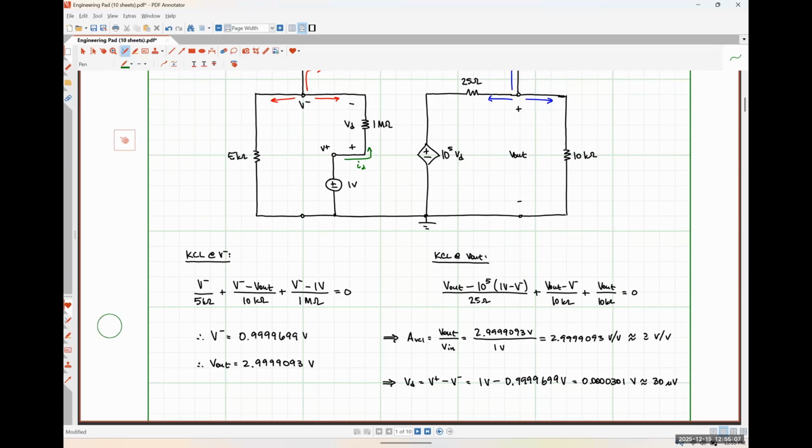All right. So now I want to find the system input resistance and the system output resistance, okay? So unfortunately, these calculations are going to be a little bit harder to do. So the system's input resistance is typically calculated, and we actually talked about this on the second class meeting, we apply a test source across the input terminals of the system with the output terminals open circuited, which means we're going to reanalyze this circuit with the load resistor disconnected. Okay.